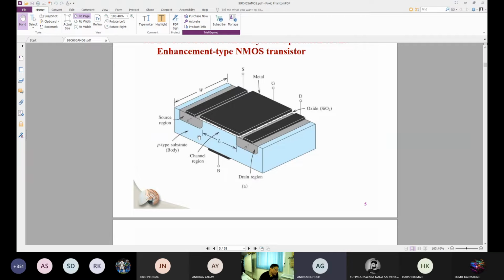in all circuit conditions. So to make this PN junction reverse biased, you have to apply zero potential here, and this is the high potential, and this is the PN junction. So the P side should be connected to lower potential, and the N side should be connected to higher potential.